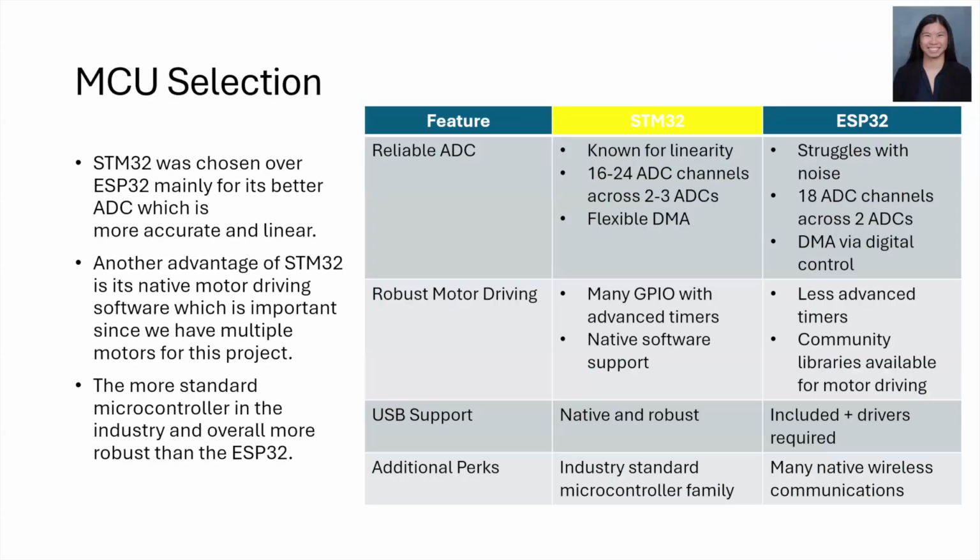For the MCU selection, we chose the STM32 over the ESP32, mainly for its superior ADC, which is more accurate and linear. Another advantage of it is the native motor driving software, which is important since we have multiple motors for this project.